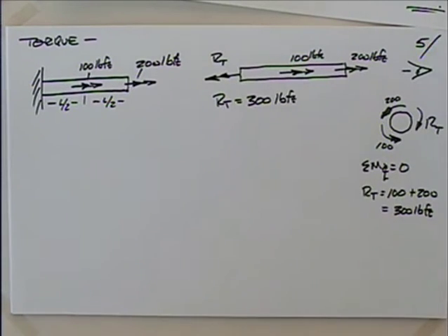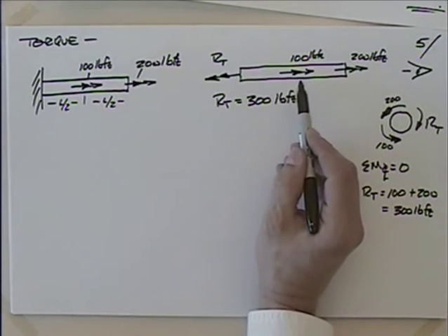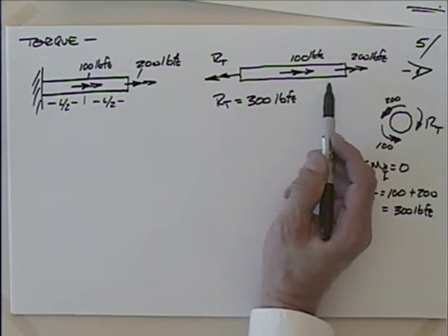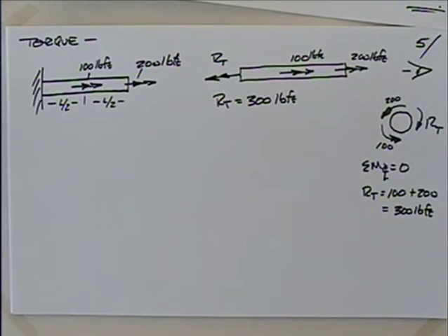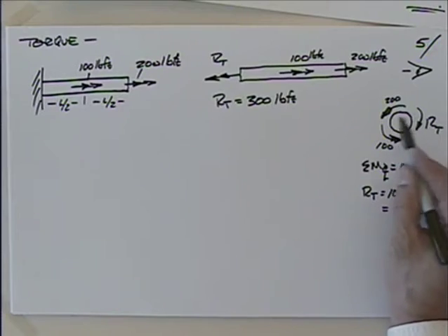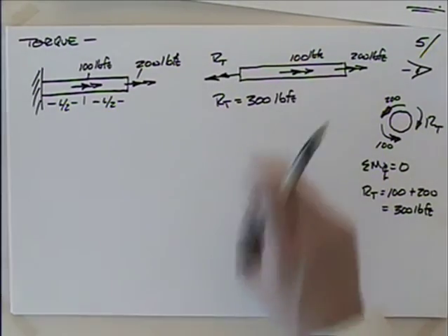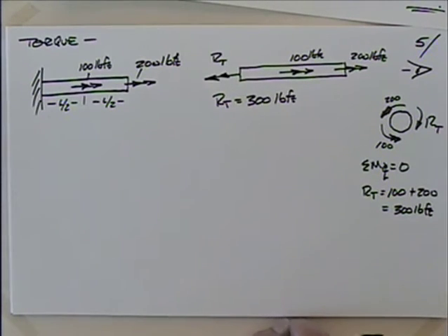And that's where, again, I don't want to commit heresy here, but you could almost think of this as an axial problem with these weird double-headed arrows, right? It's not an axial problem, but the accounting is exactly the same. This is what's really going on. You have those torques around that shaft, but you can add them up just like an axial problem.